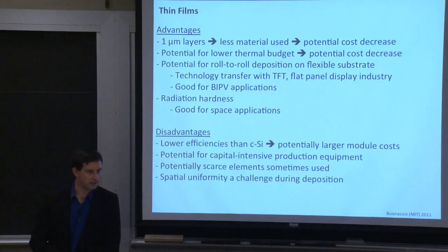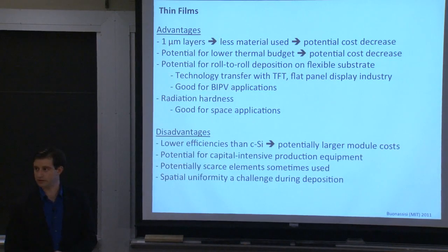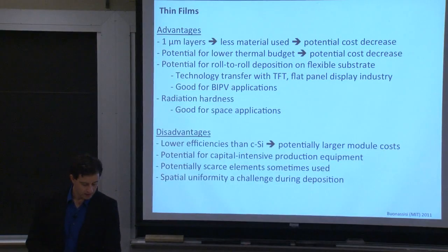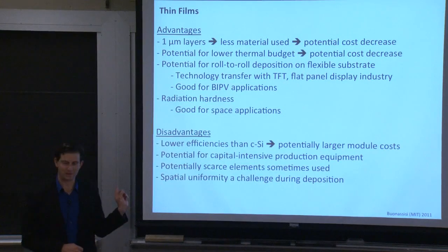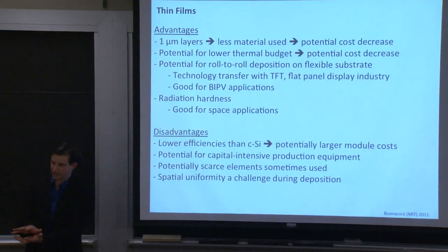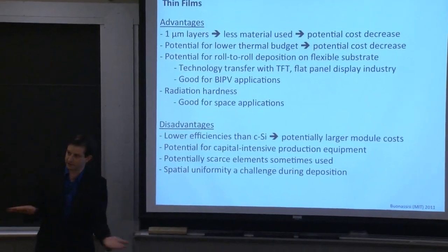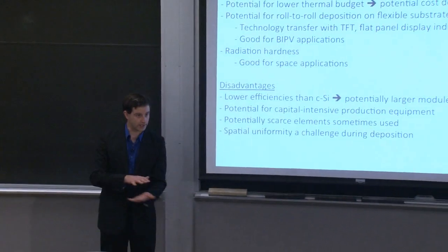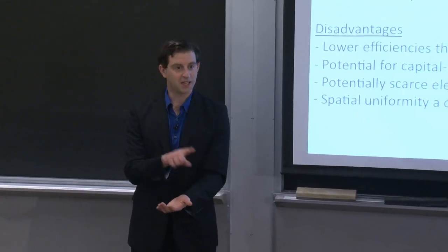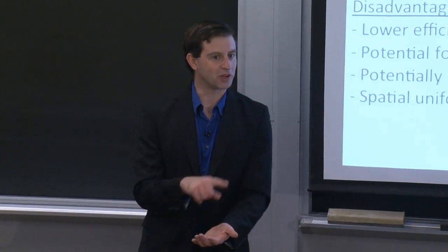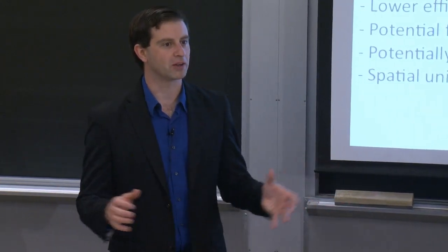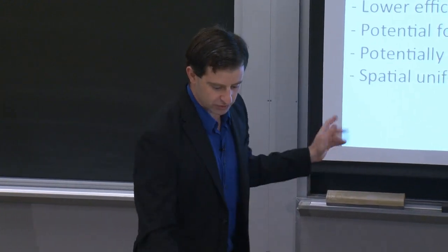And that is an engineering challenge, or a process engineering challenge, that had many startup companies flailing for a long time. Think of spatial homogeneity in the following manner. If you have one region of your solar cell that's producing a lot of power, and the region next to it is not, and they're connected in parallel through the contacts, power will flow from the good region into the bad region. Right? So you have internal current loops inside of your module that are essentially decreasing the power output of your module itself. So that's why homogeneity is important.